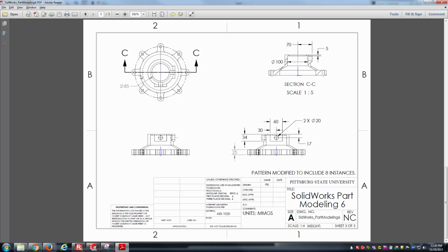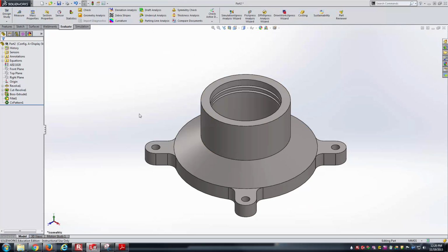One thing I need to change is the value of that global variable, right? That was 20, now it's 25. That's tied to the base height global variable. And so let's go ahead and do that first and see if we can get that going. And so what I'll do is I'm just going to come over here to the equations. I'll right click and go manage equation.